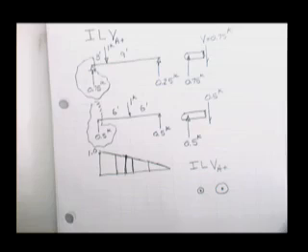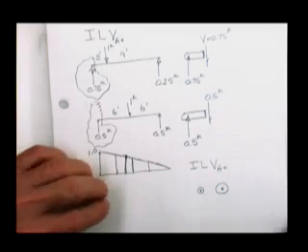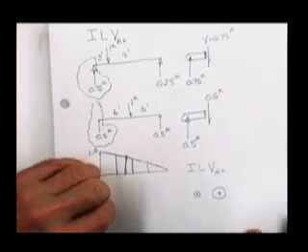Not an easy thing to see, not an easy thing to do. Not easy to know where to put a dang big old truck so that it causes the biggest moment in the beam. You've always been told the truck is here. In the real world, the truck is somewhere. And if you don't have some methodical way to find out where to put the truck, you're going to have a lot of shear and moment diagrams until you get the biggest one.